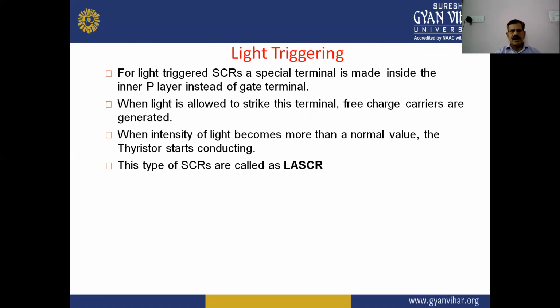Next one is the light triggering method. In this method, for light triggered SCR, a special terminal is made inside the inner P layer instead of the gate terminal.